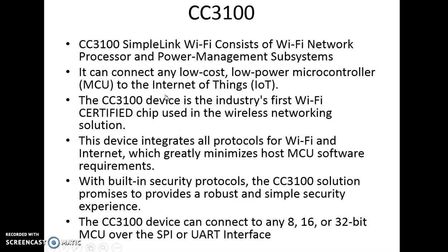There is one more advanced device, that is CC3200. It has both things, a microcontroller and also a SimpleLink Wi-Fi processor. In the CC3100 there is only a Wi-Fi processor. It does not have any microcontroller. We have to use a microcontroller with this device. And with CC3200, we don't have to use any other thing. Simply we can take sensors, interface them with CC3200, and then in that there is a Wi-Fi processor, so we can send anything over Wi-Fi.